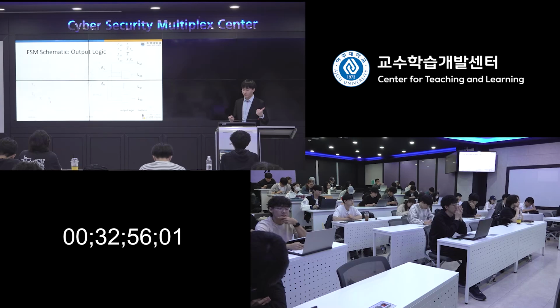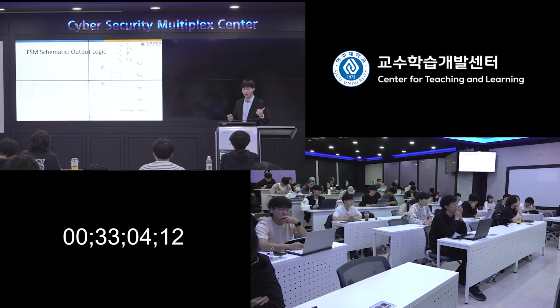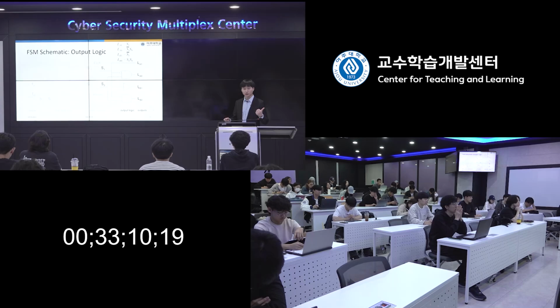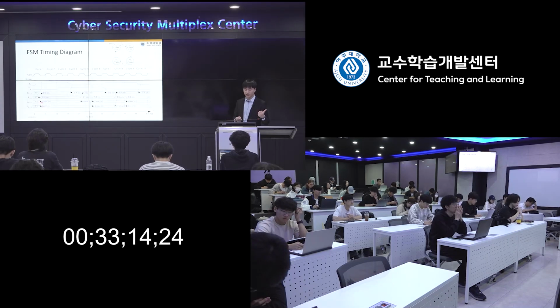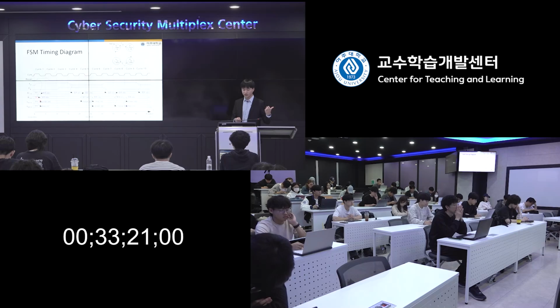If you look at here, when you put the reset to 1, S0, S1 will become 0. Then it will immediately affect the output of the traffic light control. So RA and RB, from this diagram, you will see will be switched to green and red. Whatever previous state they are, it will just switch to green and red.